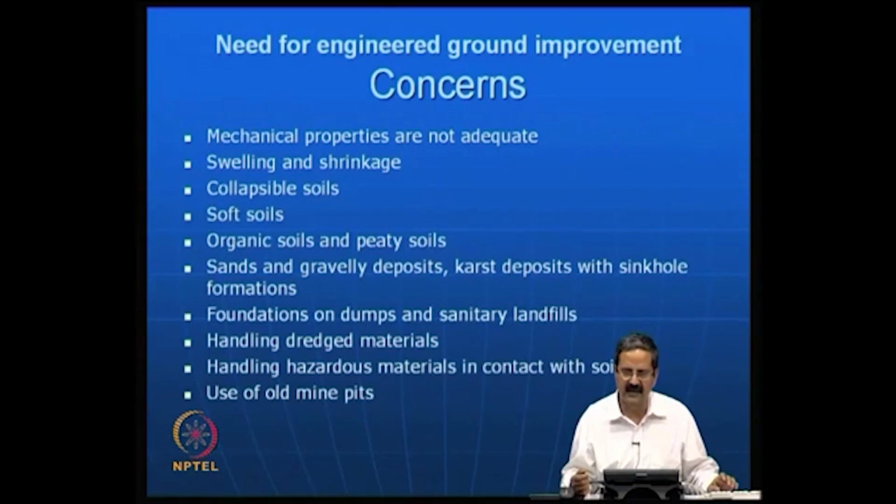You have seen a lot of cracks in buildings, pavements, dams and many structures. This is a standard problem that one has in expansive soils, particularly in areas in India like the whole of Deccan Plateau, and Chennai has expansive soils. We call them expansive soils because they tend to expand, but they also shrink, that is one problem. Then we have collapsible soils, which are another type of soil, which have a tendency to collapse because of certain conditions.